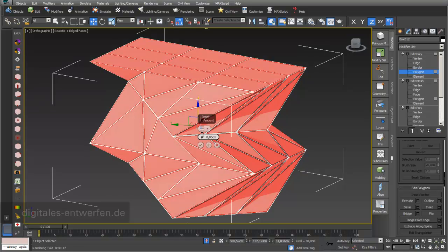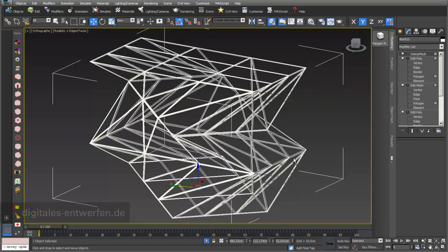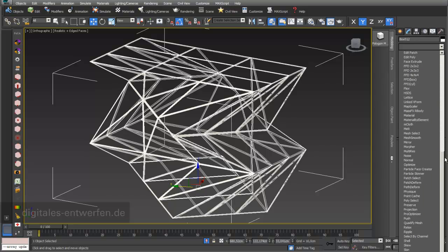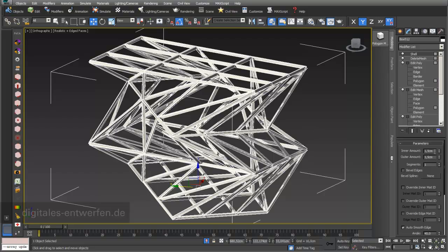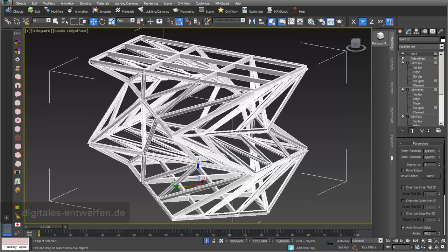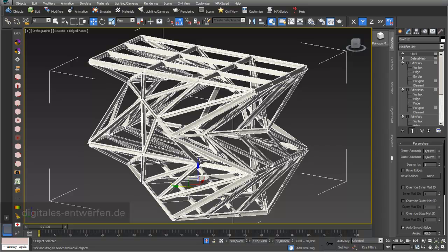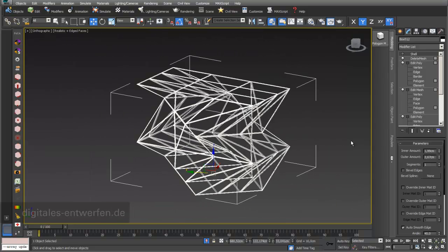Remember from last time that it was the really small geometry. I go into insert and do a small insert again. I attach a modifier named delete mesh, like this, and on top I can apply a shell modifier, and this already gives me a little bit of something. It doesn't look bad. There are not these weird explosions at the end of the day. Still something to optimize, but this is already okay as a starting point, and just a different method of producing grid structures.